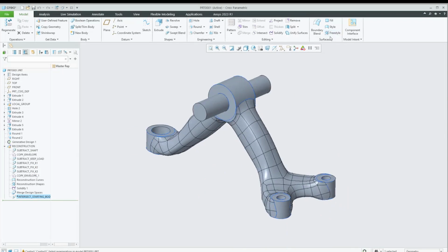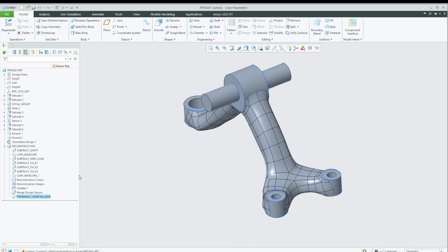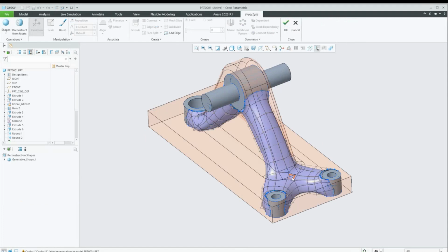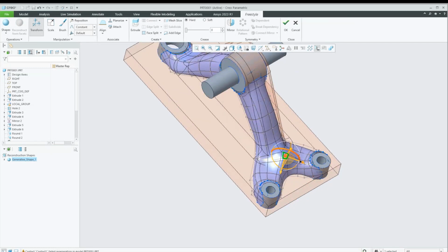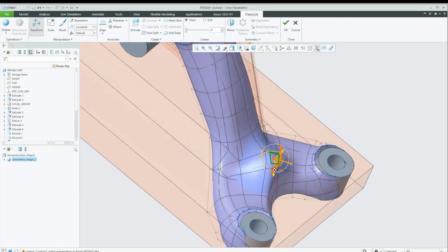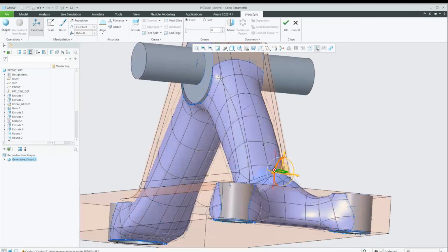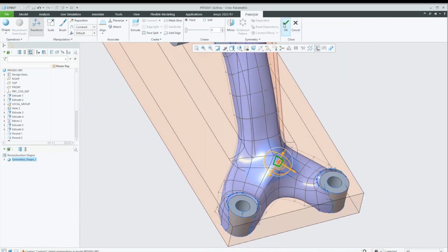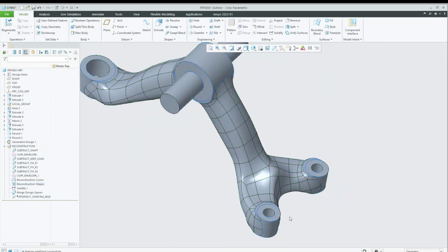For those of you who maybe have used Creo, this is a freestyle surface. And one of the nice things about freestyle surfaces is we can actually go and pick on a surface, and I can say edit. So I can pick on that surface, and then I can say, oh, now I would like to modify that surface a little. So I can literally just go in and pick surfaces. I can model, I can drag them, I can blend between them. I can do all sorts of modifications on them. And then this is now a modified CAD surface.